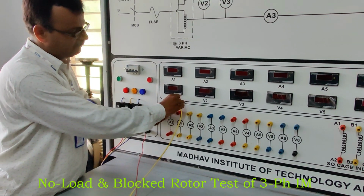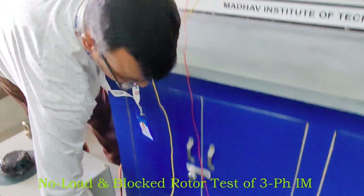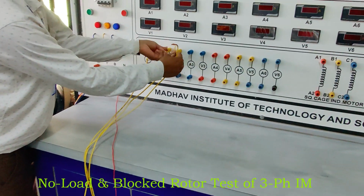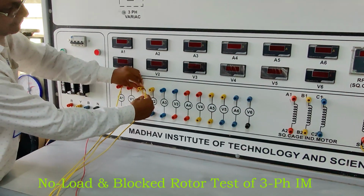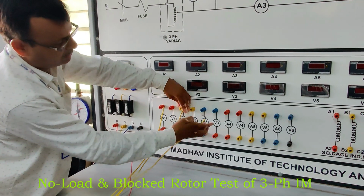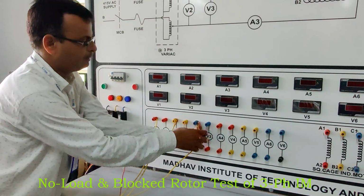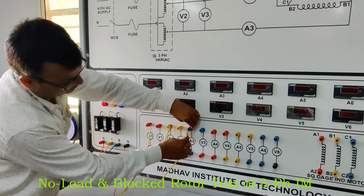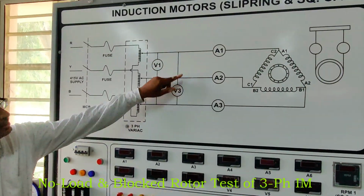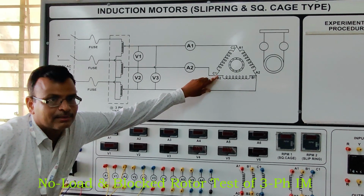The main precaution while we connect the circuit is that the connections must be tight from the safety point of view. And second, the ammeter connects here, the second terminal. And third, the A3 terminal. So these are connected in series. The second part of the ammeter, see that it is going to the stator terminals.